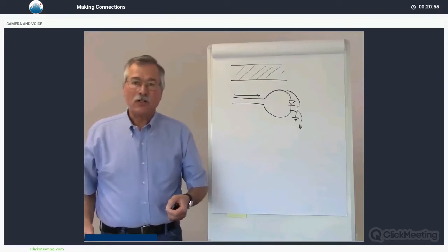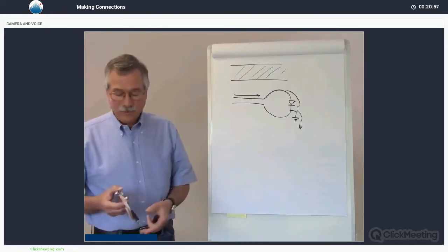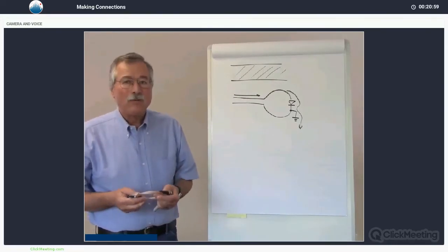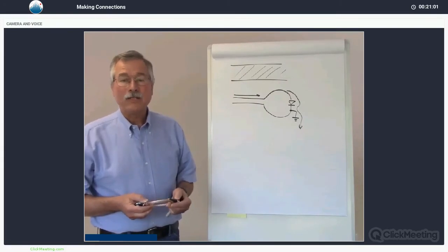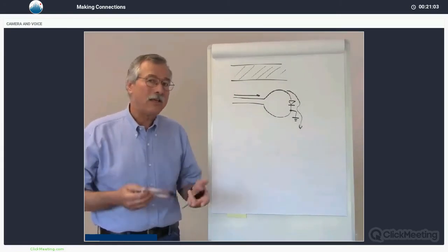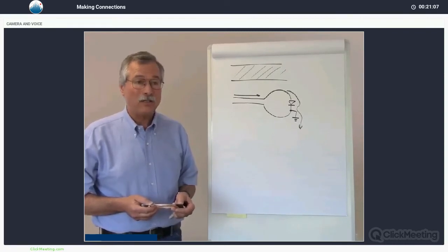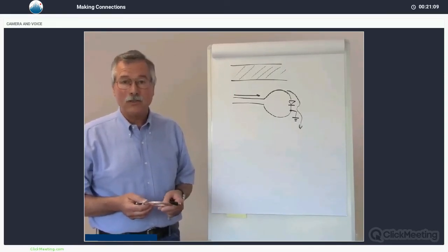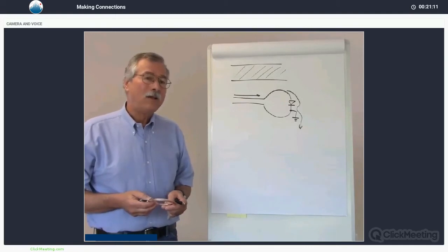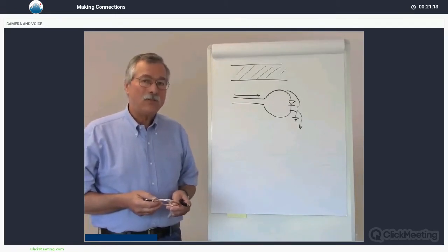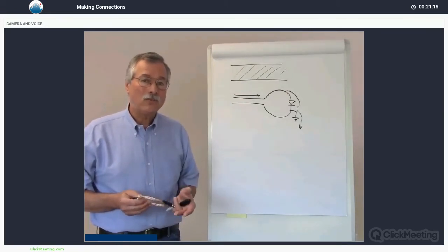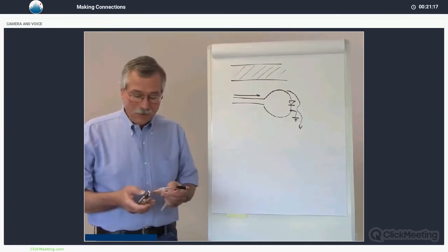So what about measuring the current of a pulse? How can we do that? Well, probably the very best indication of what the pulse looks like is from your detector. Looking at the light from the laser diode will give you a really good idea of what the current pulse looks like, and of course that's the goal anyway, to make a good light pulse. The second best scheme to use is to watch the current flowing to the laser diode.